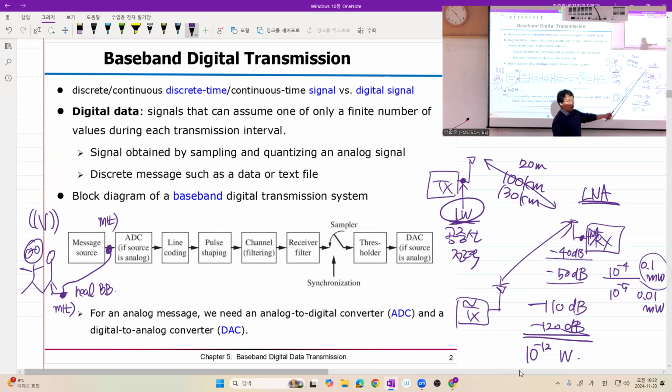This low noise amplifier not only amplifies this small received signal so that it can drive the circuit, but also, even though the name says low noise, it has a little bit of noise, and the noise is not ignorable, because noise exists whenever we have an ohmic material in our circuit. Got it? And we cannot avoid using it, right? So that's what happens.